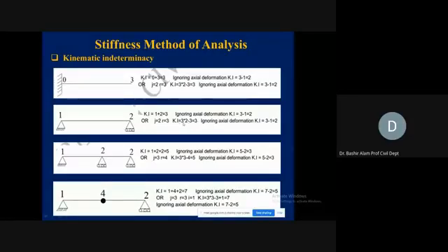So this is how we get these 3 reactions. So this is 3J minus R. It is giving you 3, which is exactly what we did by observation. And then ignoring the axial effects, minus number of members. So this is equal to 2. So again, if you see this 2 is matching with this 2 and 3 is matching with this 3. So our observation and our equation are working perfectly.